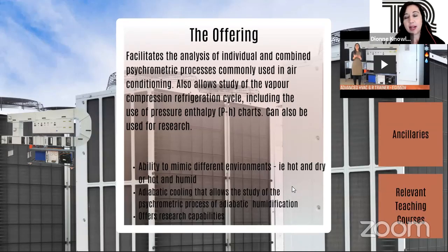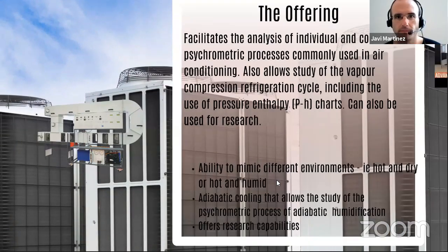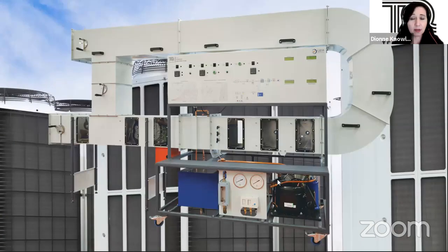Let's move on now. We're going to talk a bit about theory, but before that, I wondered if you could spend a moment talking about the adiabatic cooling, because this is something very unique to this piece of teaching equipment, and it's understanding the psychrometric process of adiabatic humidification. Javi, do tell us more about why this is important, why it's included in this particular trainer.